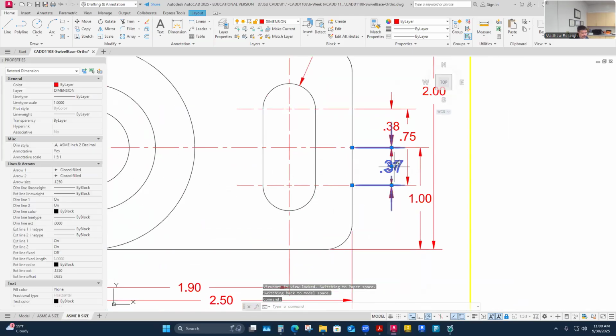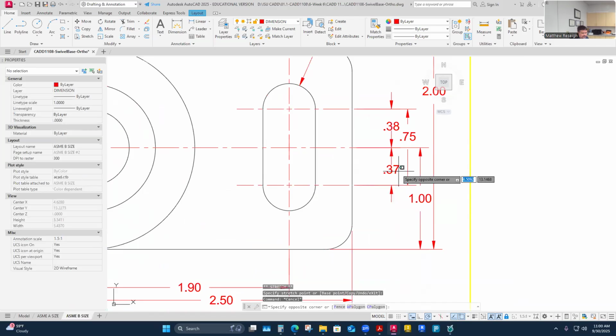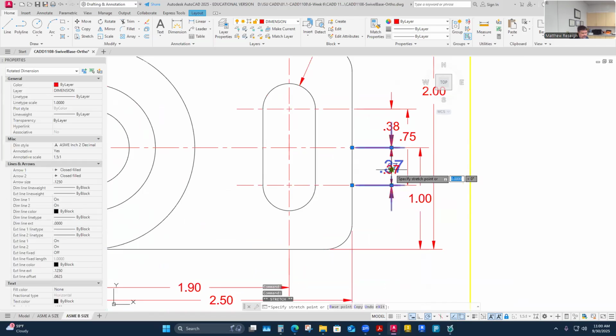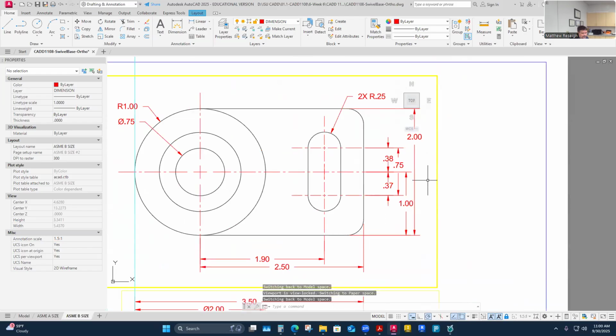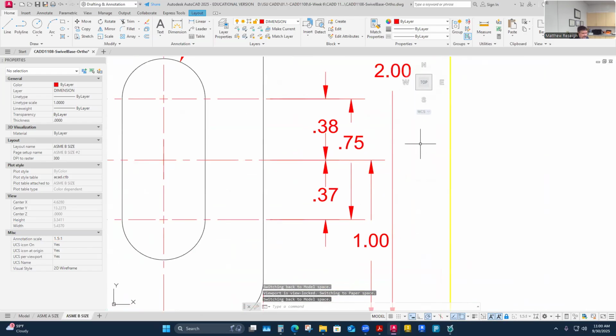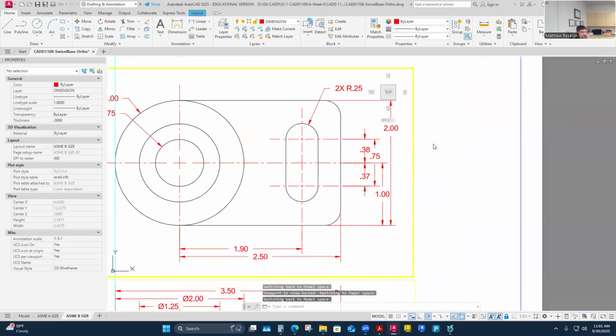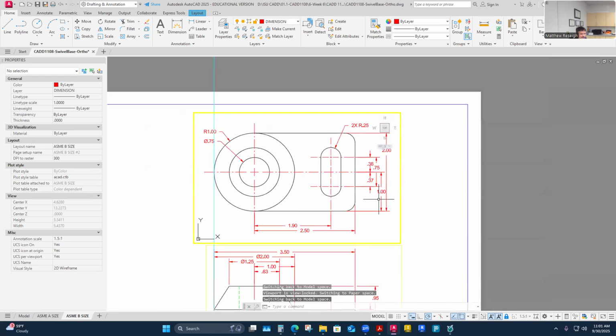This is the one I said I didn't love how this was in, it's just a slight adjustment. Which they are kind of hard to do. Ever so slight. Yeah, the question was whether I should pull this all the way out. I mean, I probably wouldn't even notice it necessarily, and it wouldn't even be wrong. I would be happier to have the dimension than not. But if I pulled that out, it would cross the one and the two. I'm trying to minimize how many extension lines cross dimension lines, but knowing that it does happen.